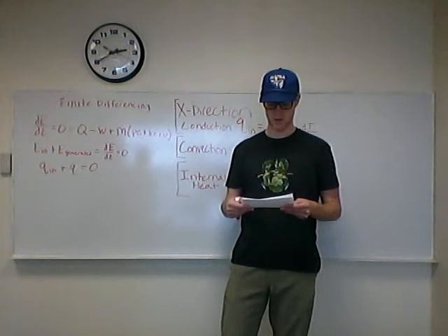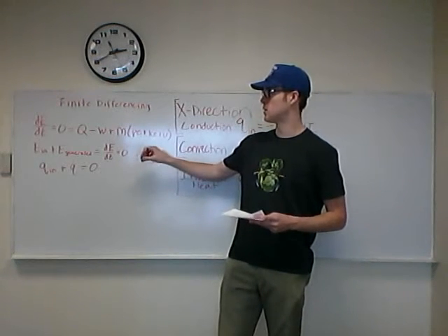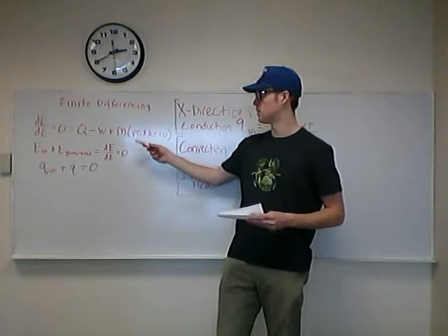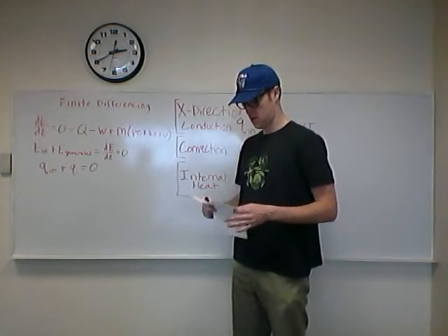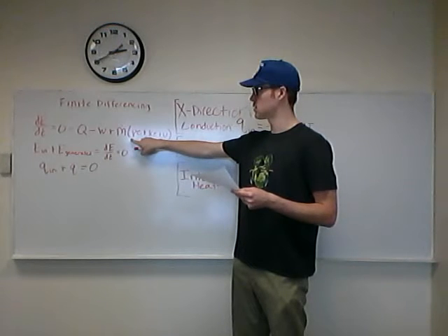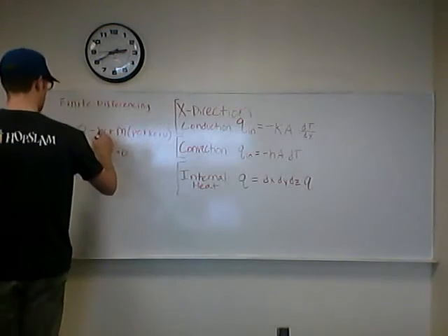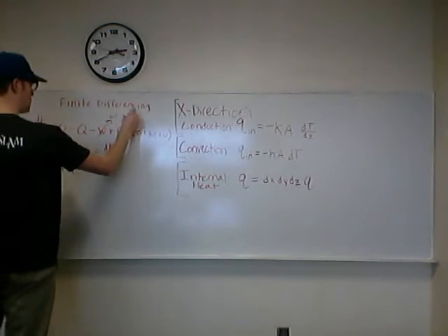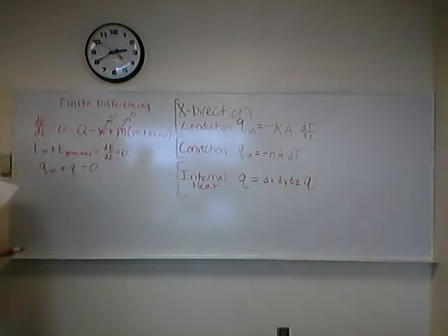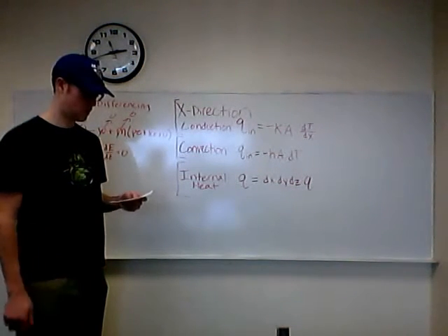A system is in steady state if the variables which define the behavior or process are unchanging in time. I will now start by showing a basic equation that we will be basing a lot of the material on today. This first equation is the rate of energy into the system plus the rate of energy generated by the system. Since the work done by the system equals 0 and the mass flow rate will also be 0, this top equation can be simplified into the equation found at the bottom here.